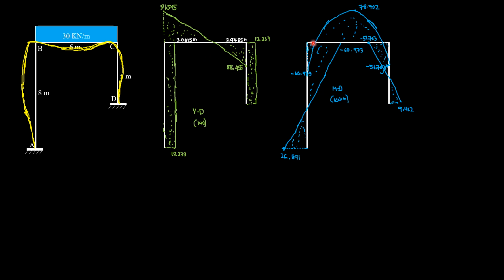Then we have negative moment, concave down first. Positive moment, concave up. Then negative moment somewhere here, concave down. Then negative moment, this one, we have a point of inflection here. So concave down. And for this portion, positive moment, concave up.